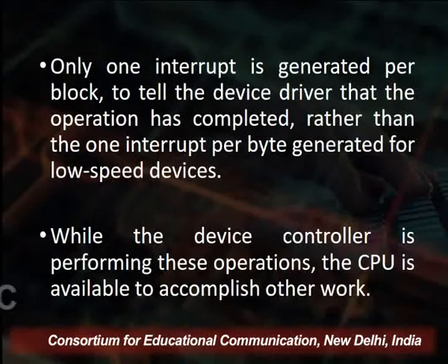So this process is known as direct memory access, and in this process only one interrupt is generated per block, just to tell the device driver that the operation has been completed, rather than one interrupt per byte which was generated earlier for low speed devices.